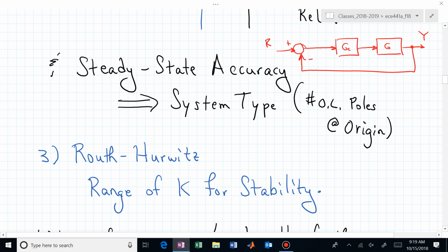We've also talked about the Routh-Hurwitz criteria. Hurwitz is necessary. When is it also sufficient? For what order of a polynomial? Second and first, right? As long as your coefficients are present and positive for a first and second order, then that Hurwitz test is sufficient for stability. Otherwise, you need more information.